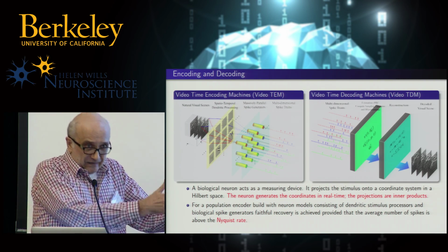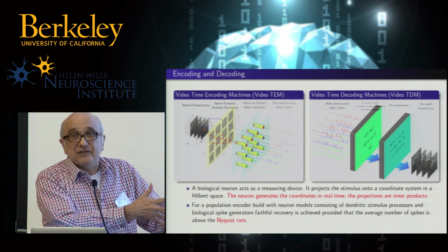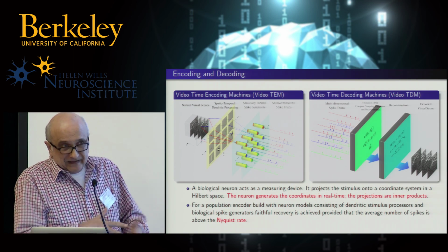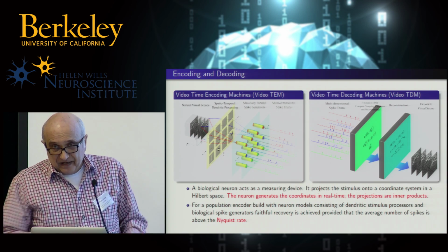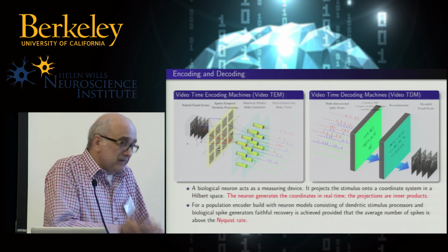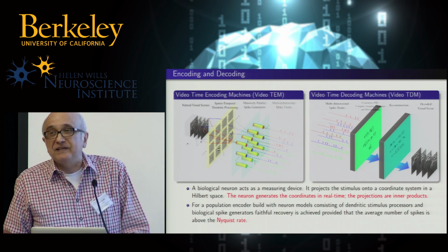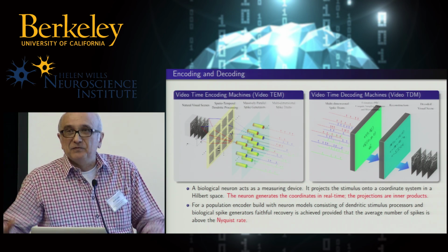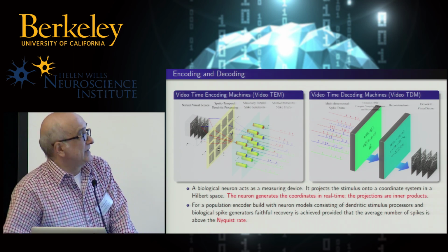And it's very clear what the implications are, when you can do something and when you cannot do something. Therefore, in vision, you have 1 million axons. Why? Because the bandwidth of the signal is 6 to 8 megahertz. In audio, you have 20 to 30,000 axons. Why? Because the bandwidth of the signal is 20 kilohertz, if you can go as high as that, okay?